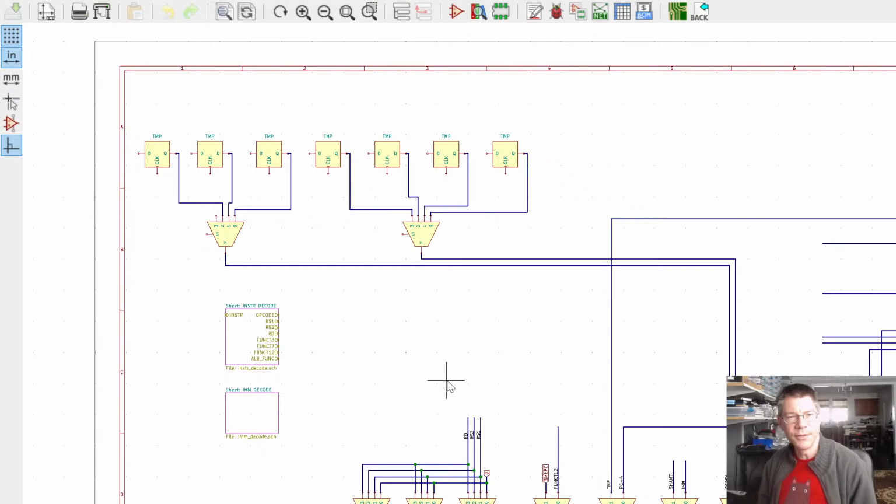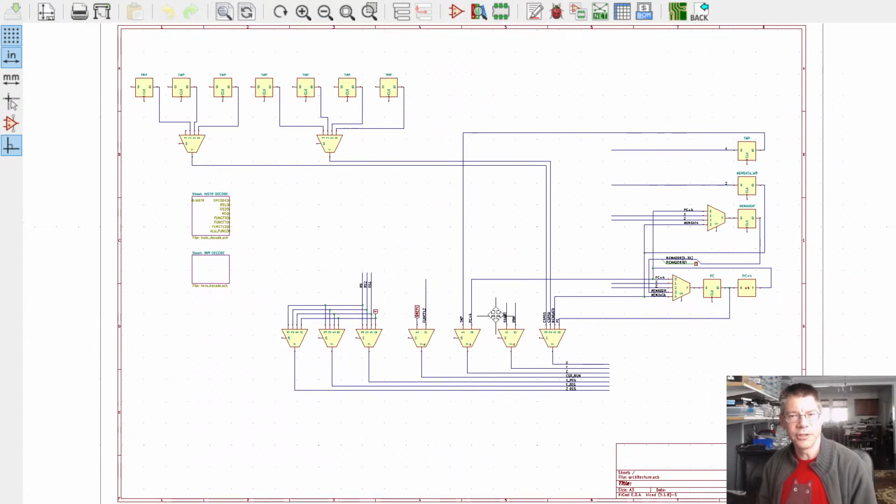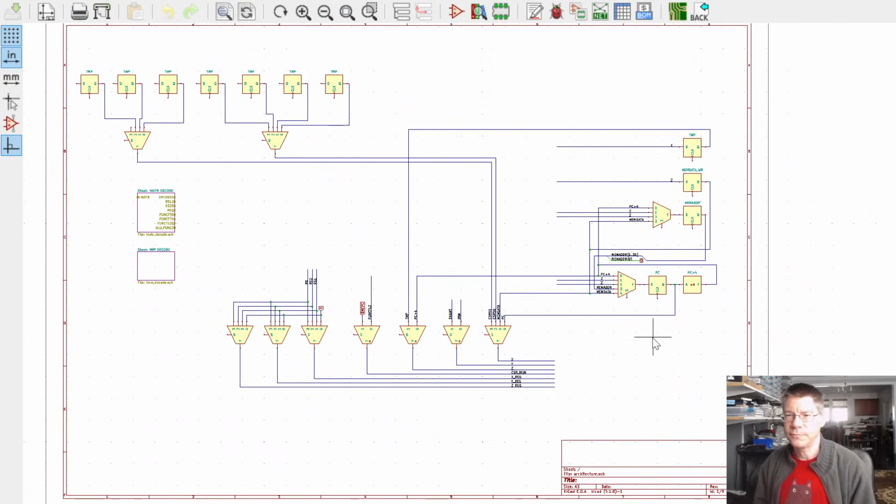Let me show you the level above this. Wow. This is pretty cool and a little small, but hopefully. How are things doing? Let me just take a quick peek. Things are pretty happy so far in formal verification land. So this is sort of like the top level of the sequencer. You can't really see it, but up at the top, these are some CSR registers. There are 7 of them that I had to stuff into the sequencer, and this was just so that I could handle interrupts and exceptions. So I stuck those up there.